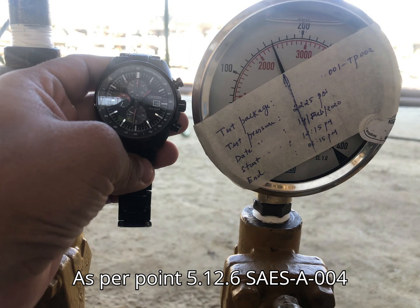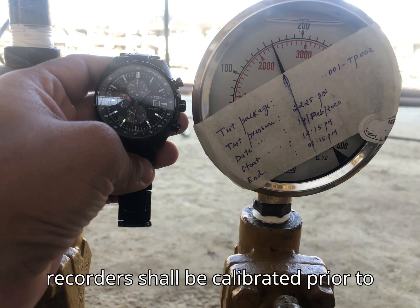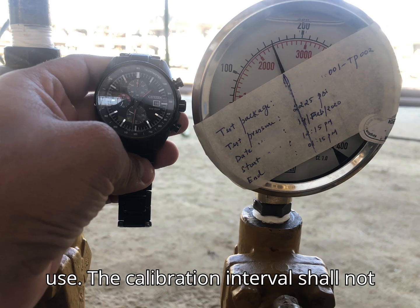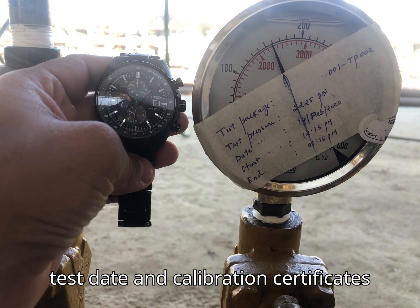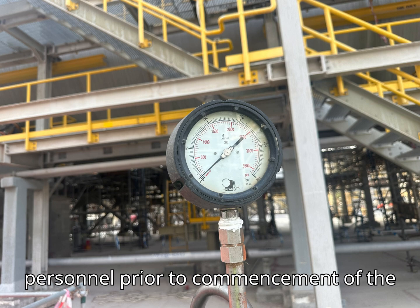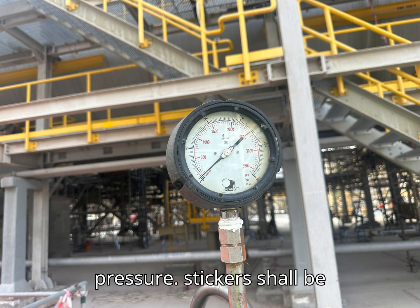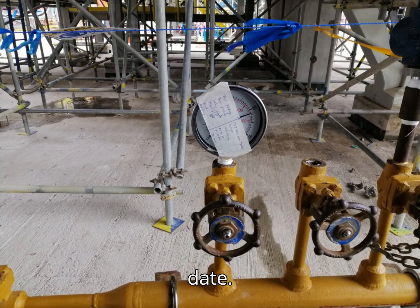As per point 5.12.6 of SAES-A-004, pressure gauges. All gauges and recorders shall be calibrated prior to use. The calibration interval shall not exceed 30 days prior to the test date, and calibration certificates shall be made available to inspection personnel prior to commencement of the pressure test. Stickers shall be applied indicating the latest calibration date.